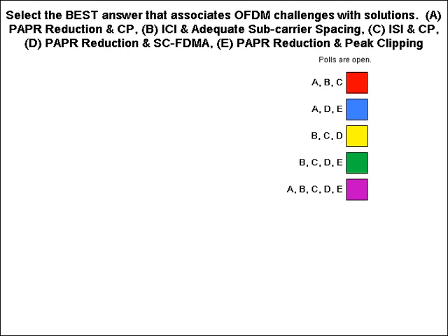That would be the easiest way of processing the received signal. So the cyclic prefix is added by the transmitter, and we could just discard that at the receiver because it may have a corrupted signal due to inter-symbol interference.